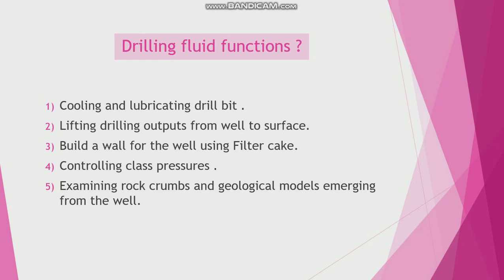Drilling fluid functions. What are the functions of a drilling fluid, or why do we use drilling fluid in drilling wells? Number one, cooling and lubricating the drill bit. Number two, lifting drilling outputs and products from the well to the surface. Number three, building a wall for the well using filter cake or mud cake. Number four, controlling pressures of the layers. Number five, examining rock crumbs and geological models emerging from the well. We will discuss every one of these functions, okay?